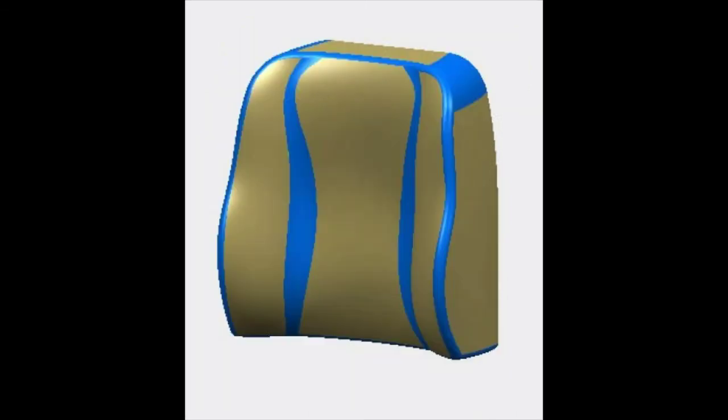The next step is to provide the fillet to the sharp edges of the solid. You can see on the image here why the smoothing of the surface curve is critical. The fillets are dependent on the quality of the surfaces that are being filleted. If there are spikes or sharp edges on the curve analysis, then the fillet probably won't run. Since the curves are smooth, just about any solid fillet, variable or constant, can be used. You can see the image.